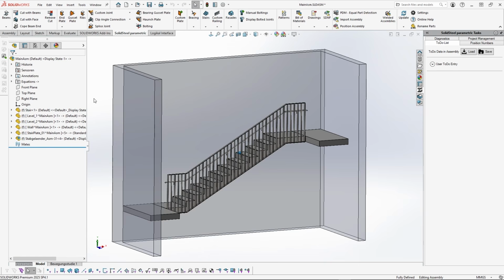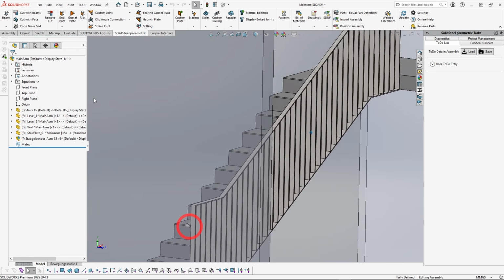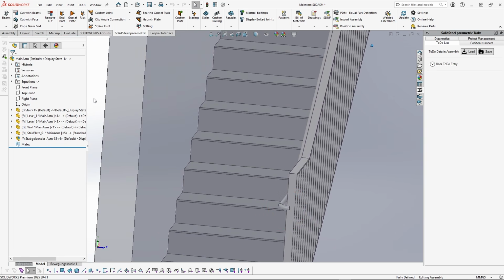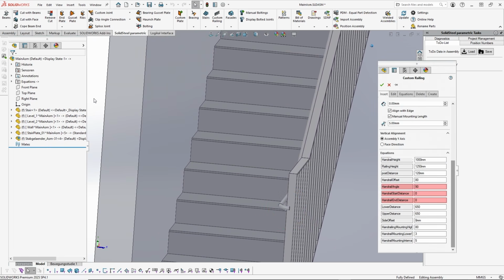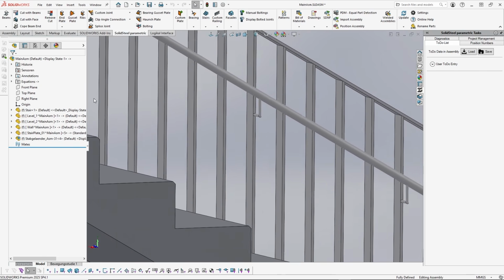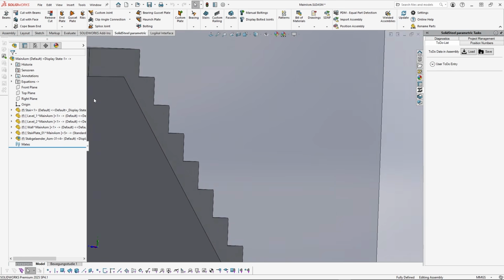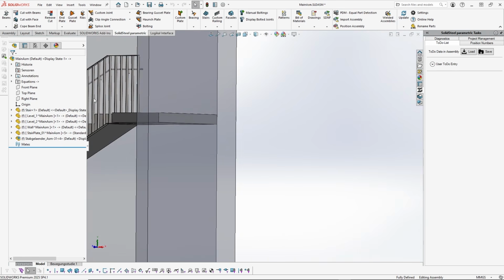Obviously we now have a railing made of flat steel, with vertical bars at equal spacing and an additional handrail. Here's a nice detail. This 90-degree bend at the end of the round tube, prepared for connecting the next handrail segment. Both the angle of the bend and the overhang could also have been defined parametrically in the dialog. From this side, you can see the handrail brackets. Their size was defined earlier using the 80 mm values. The number of vertical bars between the welded mounting points for the brackets is also individually adjustable in the dialog. There's really not much more to say, it simply works, it's fast, and it's flexible.